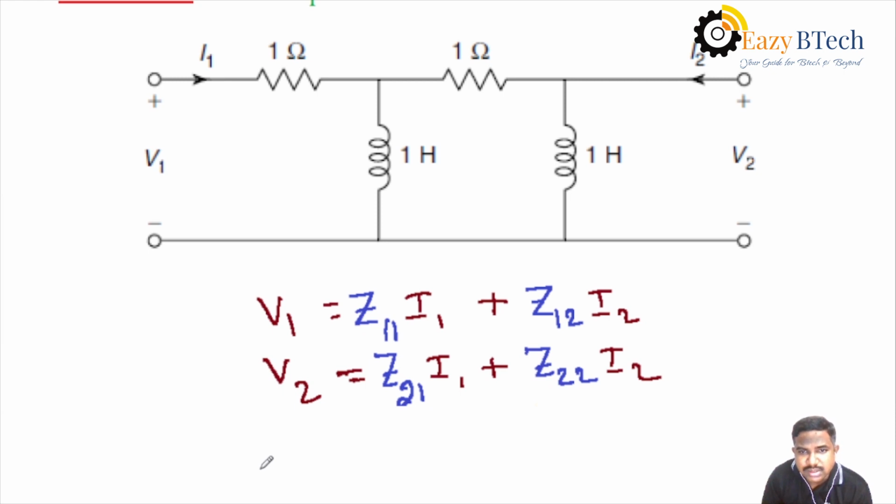The circuit consists of resistances and inductances. In the circuit, there is no capacitance value. Then what is our first step here? For the given circuit, that circuit should be changed into the transformed network. Then for resistance and inductance, apply Laplace transformation.